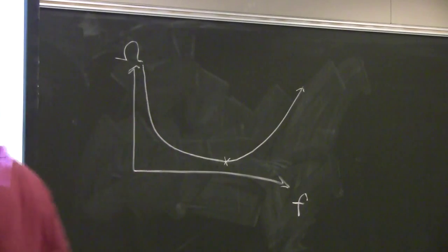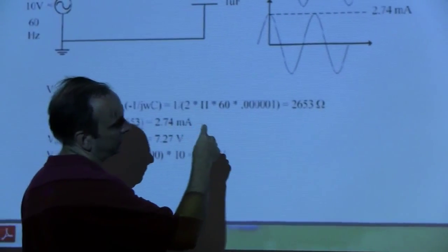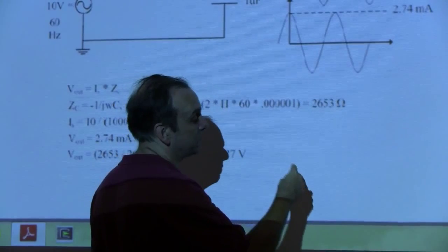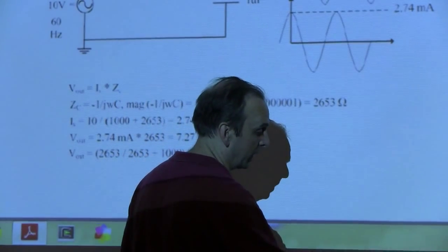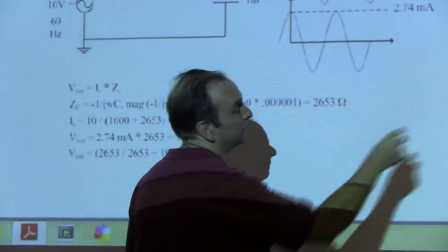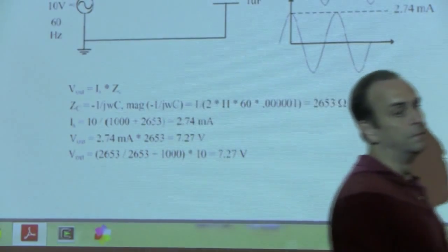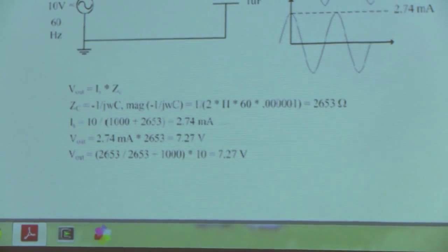So if I were to build this circuit, that real capacitor would actually function as a low-pass filter, and the output as frequency increases would get smaller and smaller until some point, past resonance, then the signal of higher energy would start to actually increase. But that frequency is really pretty high, isn't it? Depends on the capacitor.